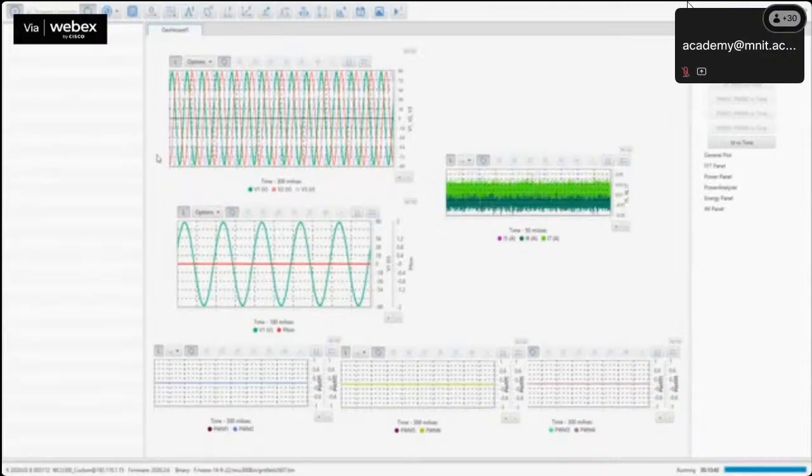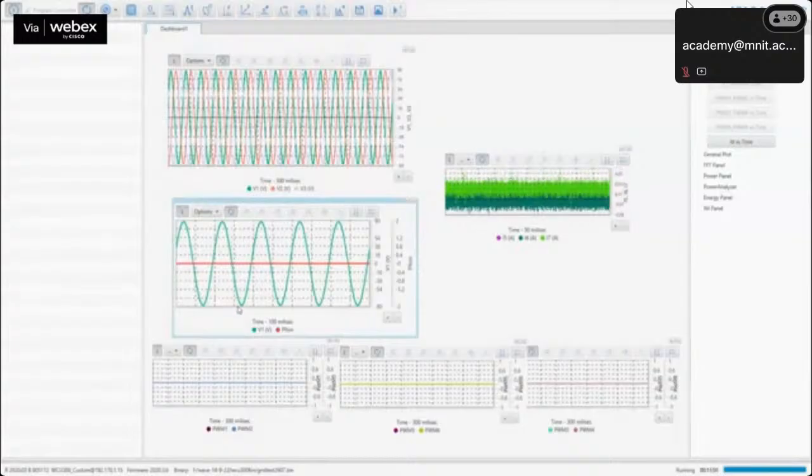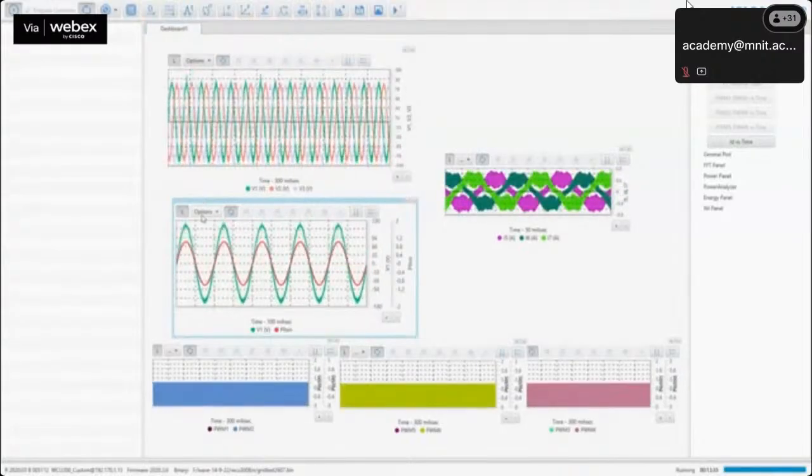Subsequently, in order to interface the scaled down hardware prototype of the VSG, it is first synchronized with the grid by enabling PLL. This panel displays the 3-phase grid voltage by enabling PLL. It can be observed that the VSG voltage is synchronized with the grid voltage. Subsequently, the current output from the VSG can also be observed from this panel. The system is under steady state condition currently.